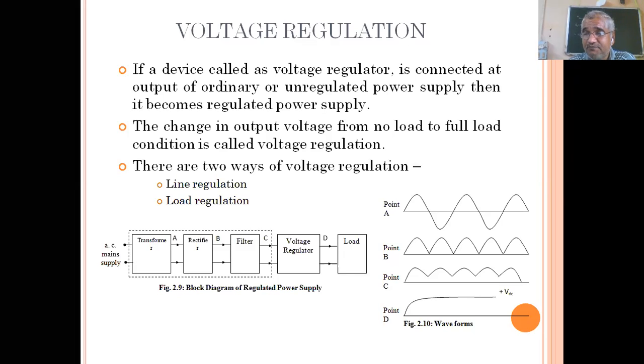If the MCB voltage changes, even then the output voltage should be constant. Or even if the load we have applied changes, the output voltage should be constant. And who does the work of keeping this constant voltage? It is the voltage regulator. The voltage regulator is the circuit which maintains constant output voltage irrespective of change in line voltage or change in load current. So using these four